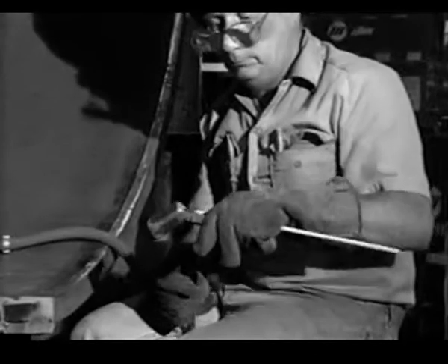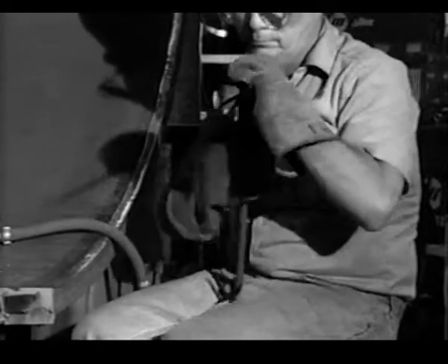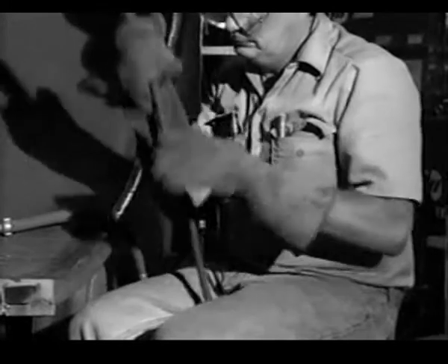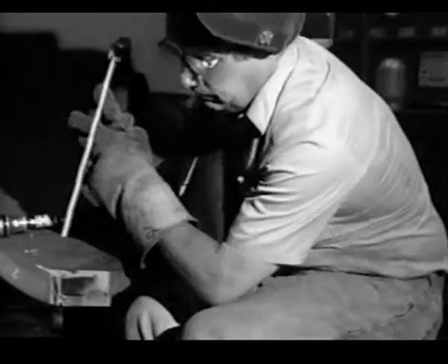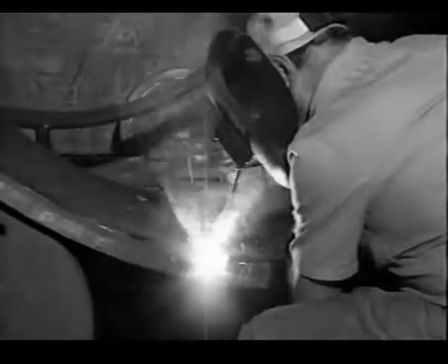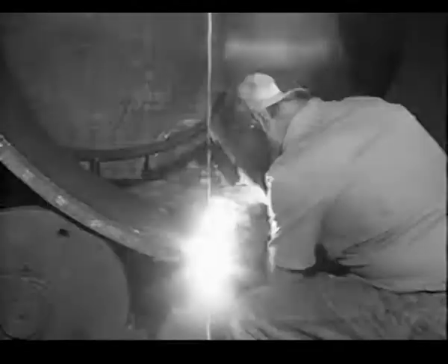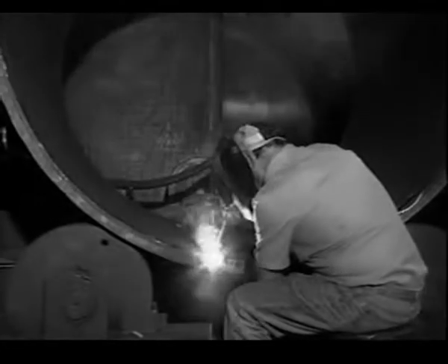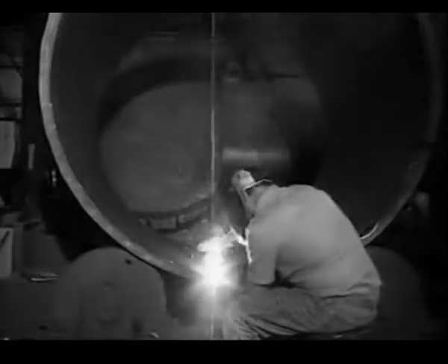The bare section of the electrode is clamped in a holder, which is connected by a welding lead or cable to a terminal of a constant current power source. The workpiece is connected to the other power source terminal. Touching the tip of the electrode against the workpiece and withdrawing it slightly initiates or strikes the arc. The heat of the arc melts the base metal in the immediate area as well as the electrode core wire and covering. The molten base metal, core wire, and metal powders in the covering coalesce or fuse to form the weld.